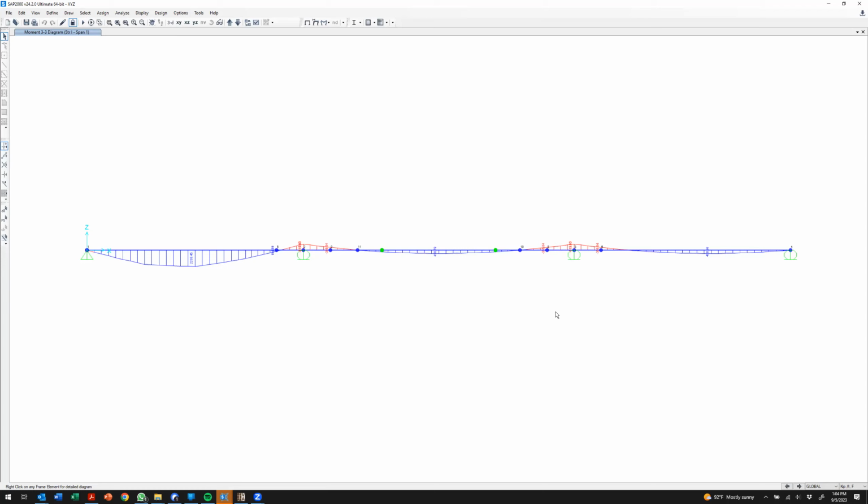All right. I actually have a question here. Sure, go ahead. If we were to add point loads, could we also just add nodes at those points and then add node loads? Would there be a difference in that? The short answer is yes, you can, but you have to do a few things to make that work. If we just add a node, you have to connect that node to the members. And SAP is pretty smart about doing that. It'll detect that there's a node there and it'll split the member and connect the member automatically. Visual analysis is less smart when it comes to that.